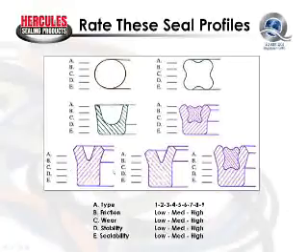Now, the bottom row of seals are all rectangular in shape. That is, the height of the seal is greater than the cross-section. Our stability is going to be extremely high. This seal is a symmetrical seal. You look at the thickness of the seal lips. We're probably going to be around a 6 or so with this particular seal. The friction is going to be medium-high, wear is medium-high. Stability is very high, which is going to improve the overall performance of this seal.